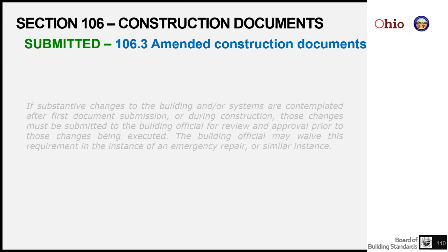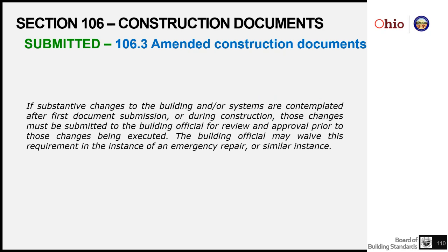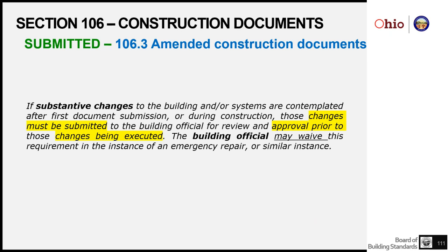If a drawing is amended or construction documents are amended after they are first approved, and they would be substantial changes, they must be resubmitted to the building official for approval prior to executing that work.